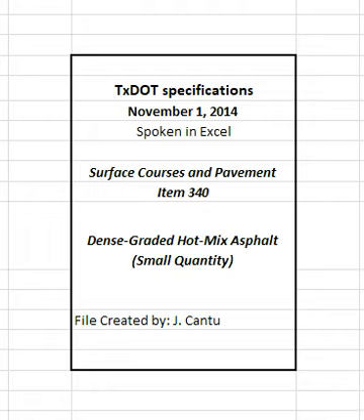The engineer may require additional information to be marked on the core and may choose to sign or initial the core. The engineer will take custody of the cores immediately after they are trimmed and will retain custody of the cores until the department's testing is completed.